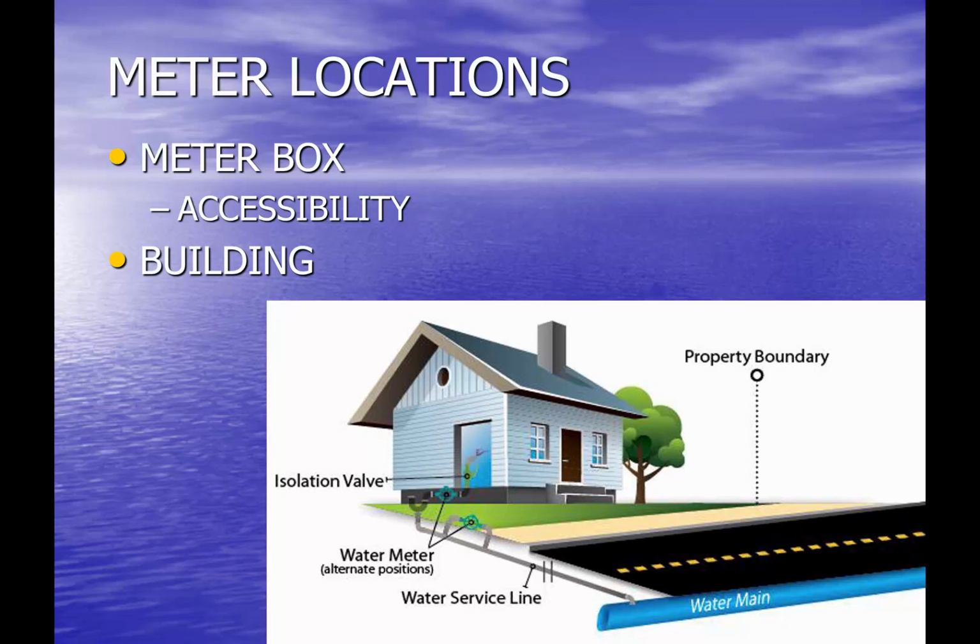It does become more challenging when you have metering constructed in that manner. They become more difficult to prevent illegal connections upstream of the meter. So if someone has a long service line that's before the meter, they can tie into it and essentially steal water. So that's a challenge. Again, you'd want to have that curb stop at the property line or in the parkway to allow shutoffs, but it certainly brings challenges in meter reading if you've got meters that aren't really accessible. So if it's in a building someplace, then we need to communicate with the customers every time we need to go read that meter.